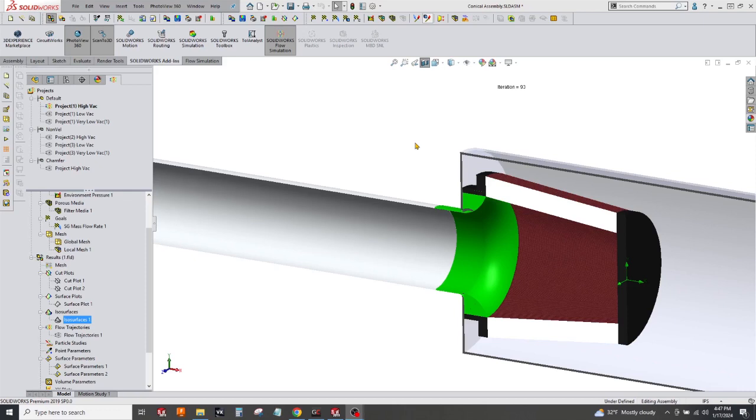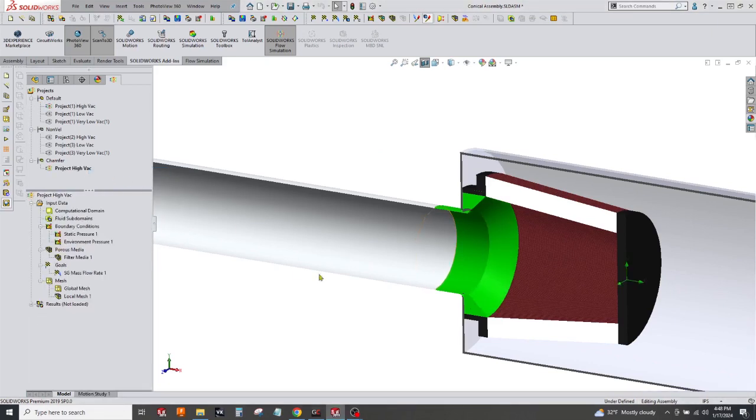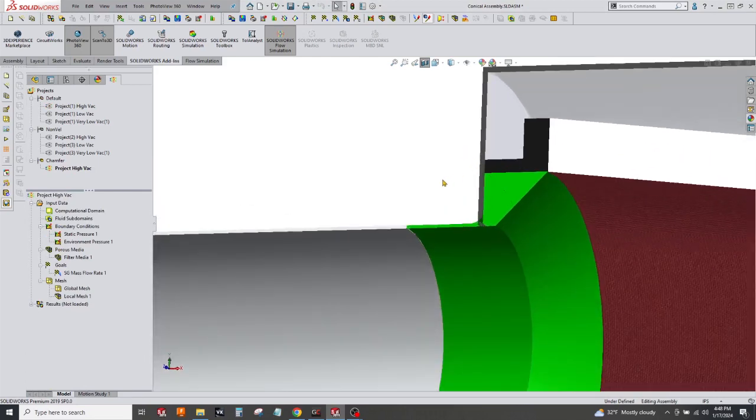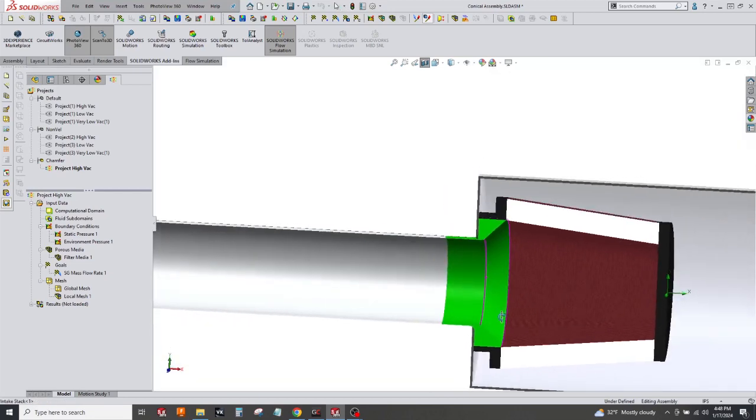But I know what you're thinking, like this is probably kind of complicated. For some people, you're not going to have access to all this fancy stuff to come up with this perfectly optimized fillet and figure out if it's working or not. So let's look at something here like a total hack job. I don't have a lot of options and I'm just going to do something really simple. I came up with this guy and it's just a chamfer. It's nothing fancy. It's a 45-degree chamfer. You could seriously just get out a file and go at this thing and end up with this.